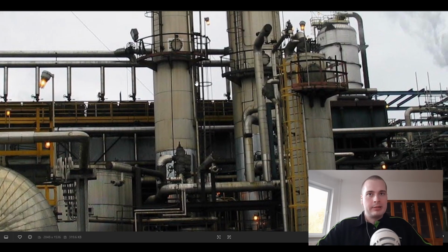The problem with dead legs is that the liquids or the gases don't flow inside of them. So in the winter, in those places where there's no flow, you can actually have liquid or gas freezing or condensing. I've actually participated in a couple of projects where we worked on dead leg mitigation, and another project where we worked on heat tracing the dead leg, meaning that we were installing electrical heat tracing onto the pipe to keep it warm in winter.